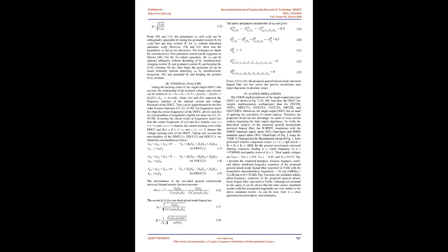With respect to references 7 and 10, the proposed biquad filter uses the same number of active elements, but the proposed circuit has the following advantages: fewer component matching conditions, the use of only 2 grounded capacitors, and no switches.